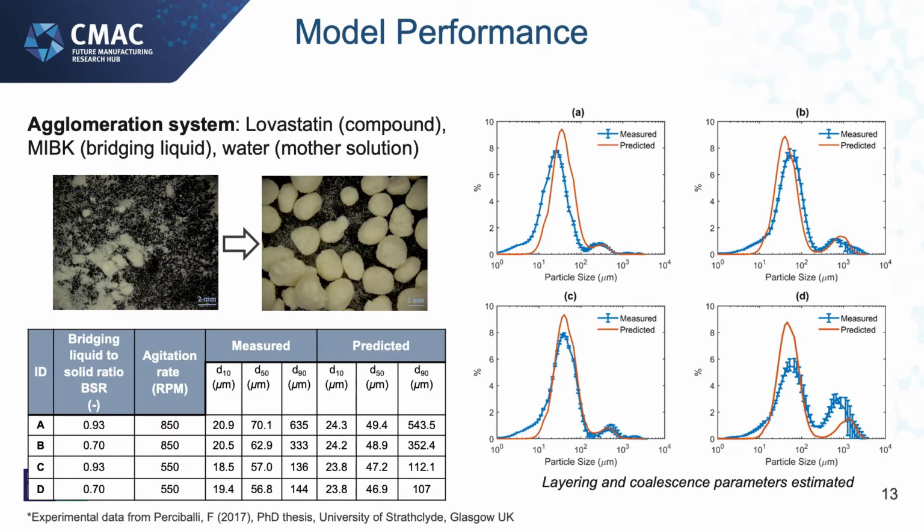We also looked at the performance of the model. So we tested this for a lovastatin agglomeration system, which consisted of MIBK as bridging liquid, and water. This was taken from data from Francesca, previously from her PhD at Strathclyde. We did some checks as well within Sheffield, but we found generally good agreement of the model with the experimental results. There were some slight discrepancies, which could be due to other mechanisms that were yet to be developed and included, such as breakage and attrition. But overall, we saw pretty good agreement with the material system of study that we investigated.